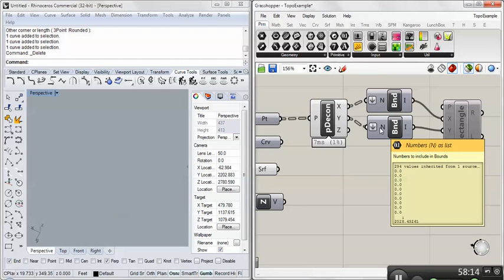Anyway, flattening, grafting, they're like the weirdest labels ever. I don't know why. I guess they fall under the idea of tree, graft branches on, and I don't know. Flatten doesn't make sense to me, but it is there. Hopefully you don't have to use it too often, since Grasshopper's designed so you don't have to, but understanding why it's there matters. So like right here, we want to know the entire boundary of that set, not just each row. That's where you have to kind of understand it so you can manipulate it when you have to.